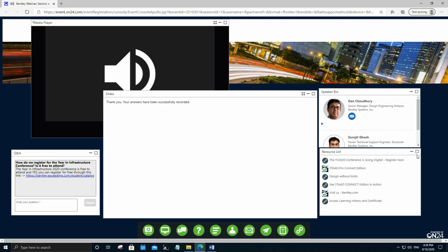You can do that if you want to just reduce the analysis time, but that totally depends on you. If you want, you can just use a separate model, meaning the same model with the basic load cases only, the static seismic and the dynamic load case, and find out the scale factor from there. Or if you want, you can also put that static seismic load case in the same model that you are using for the analysis and the design purpose. So that depends on your requirement.